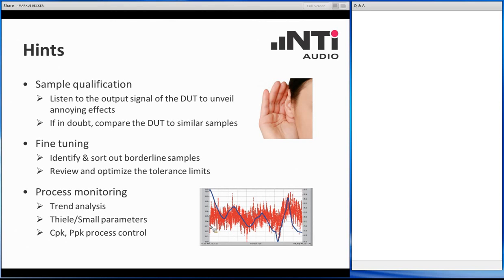And here you can see there is a certain fluctuation. There is a second curve, the blue one, overlaid. The blue one represents the ambient temperature. Now this gives us, for instance, the hint that there is a certain dependency of this measured behavior on temperature. And that brings us to the conclusion that we should probably recalibrate our whole test system from time to time, especially if the ambient temperature changes by maybe 2 or 3 degrees, just to make sure that this effect is compensated.